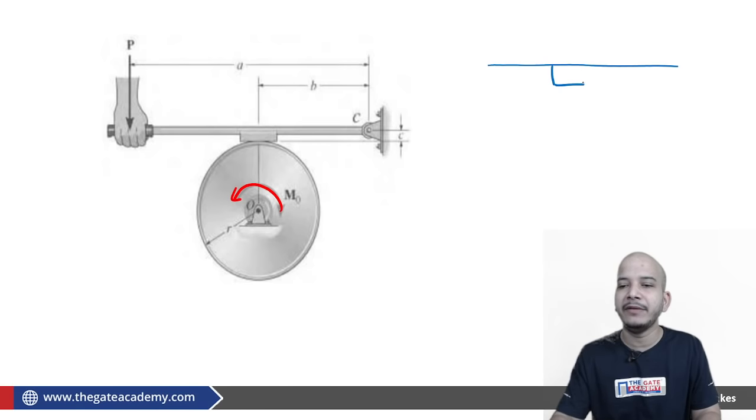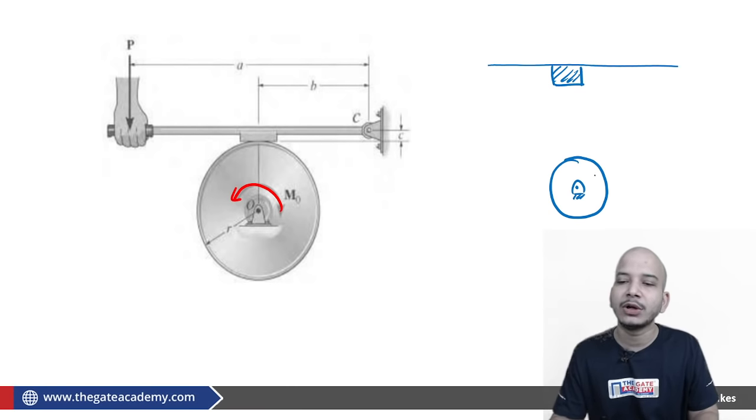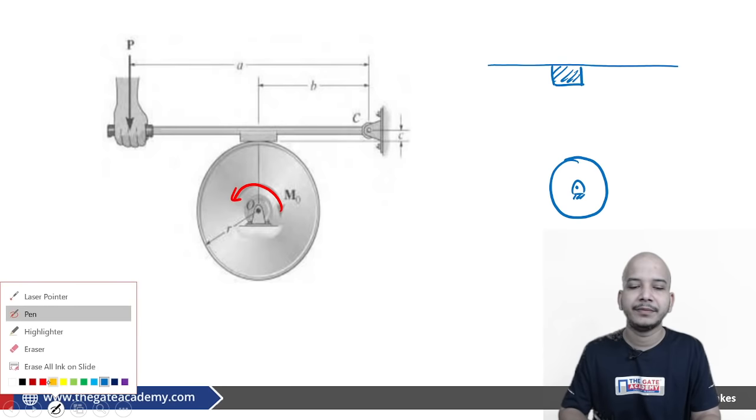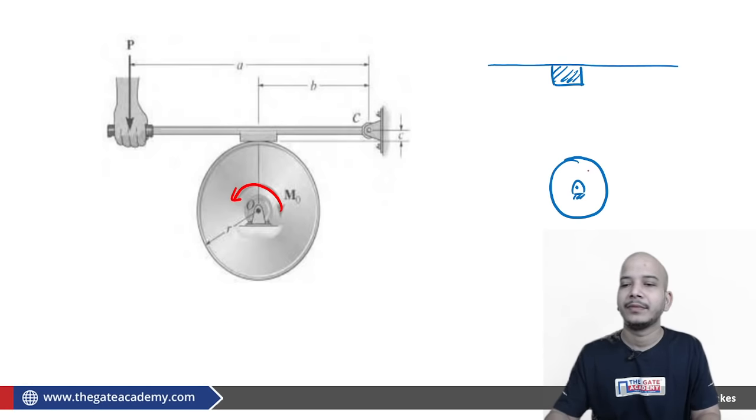Once again, the FBD will be of prime importance because the rotation sense is counterclockwise. The friction which will come on the drum will be towards right in this particular case. Normal action, we can complete the FBD now for the block drum arrangement as well.